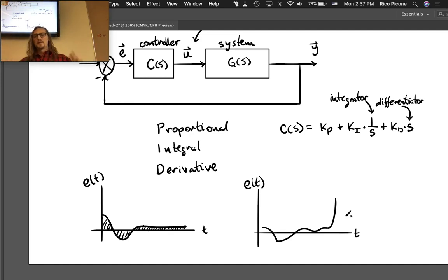Something big happened. So what we want to do is react to that, right? We want to restore back. But the integral one is just integrating away, so it's not going to be very affected by this immediately. The proportional one is going to take a little bit until it gets high enough to really kick in. So we want it to react quickly. So what we do is we have a derivative term. When the slope of this gets high, that means the restoring force can immediately react to changes in the error that happen quickly.